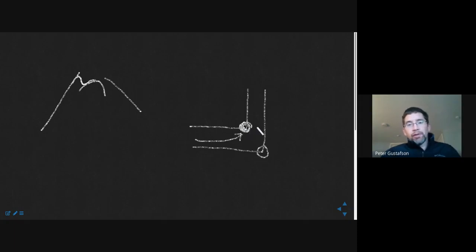If you wanted it precisely, because it's a stress concentration, you would have to do a finite element model or something else that would be similar. Now, that gets us to some practicalities, right? So if this were an ideal corner, and this were an elastic material, you'd get what amounts to an infinite stress concentration there. But then I would go back and argue, well, David or whoever made the claim, yeah, it's infinite.